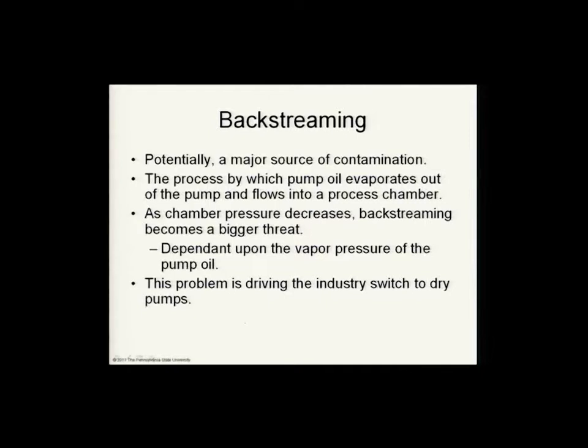Backstreaming, the oil coming back, that's potentially a major source of contamination. As we said, that can be very, very bad. You can imagine oil molecules getting on the surface of the sample you're working so hard to control. And so the pump oil can volatilize, that is, some of the molecules can turn into a vapor, and they can bounce their way back to the process chamber.